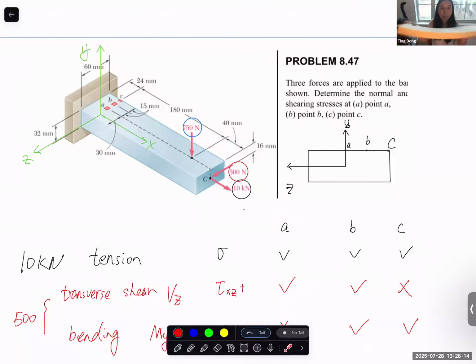and also clamp the bottom surface, and this will generate a positive sigma y. Does this make sense or not? But with bending, no matter which axis you bend about, it's always the normal stress in the x direction. To really generate sigma y, you push or pull in the y direction. Why would you want to clamp the beam at the bottom and apply a force? In civil engineering, yes, you clamp the bottom part and apply force, and it's a compression sigma y. Yes. Thank you. You're welcome.